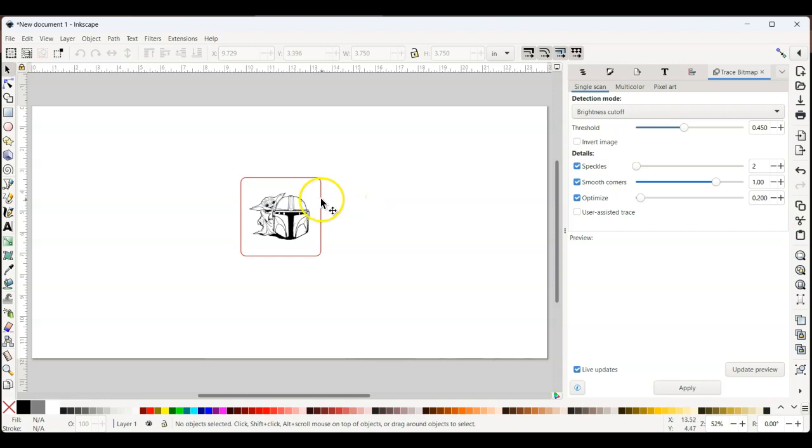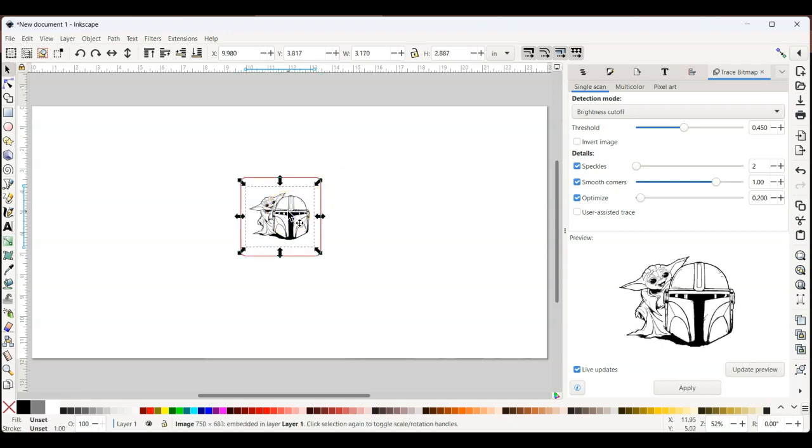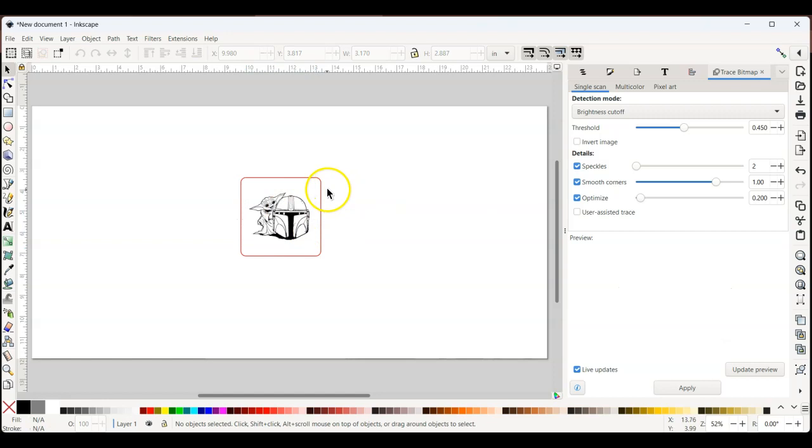So why did we make the outline red? As I said a moment ago, the laser color does not print in color. It's just going to burn and cut. For the laser software, which you're not going to learn, that is something I'll do on the back end when I'm making your stuff. The red line indicates a cut line. The black colors indicate engrave. So it knows the difference. It'll know that red means cut and black means engrave.